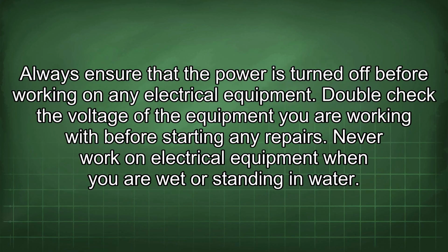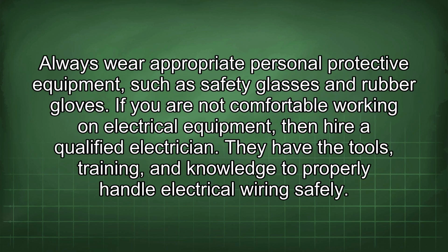Always ensure that the power is turned off before working on any electrical equipment. Double-check the voltage of the equipment you are working with before starting any repairs. Never work on electrical equipment when you are wet or standing in water. Always wear appropriate personal protective equipment such as safety glasses and rubber gloves. If you are not comfortable working on electrical equipment, then hire a qualified electrician. They have the tools, training, and knowledge to properly handle electrical wiring safely.